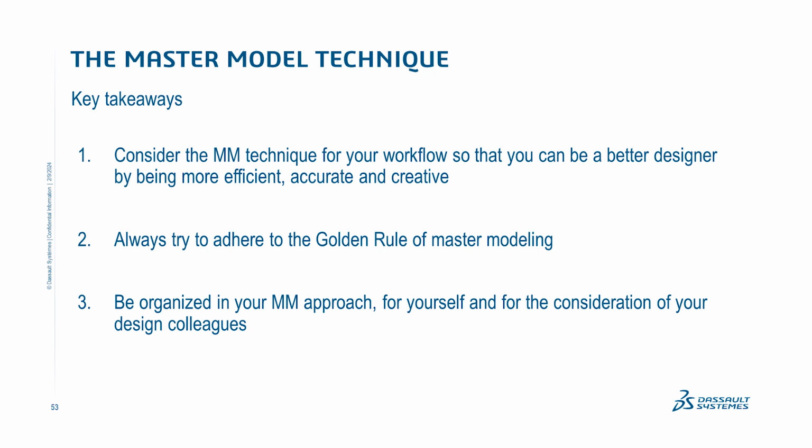And then third, be organized in your master model approach. Consider not only yourself, but your colleagues. I mean, you're going to work on this master for quite a while. It's going to be quite a few features, and then you're going to go away, and for a few months you might come back to it. If you're not organized, you're not going to really understand it, even for yourself, let alone your colleagues. So a very important point. I really strive to make my masters very understandable, and it'll pay off.